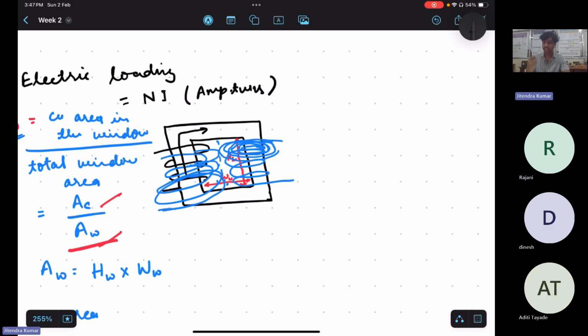Eddy current. And that is why you have eddy current losses in a transformer core or in any core where flux is flowing. To avoid those eddy current losses, which can be significant, we keep multiple laminations sandwiched between insulations, so that eddy current should be avoided.